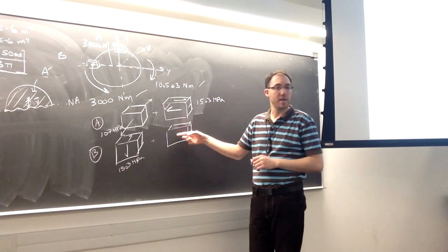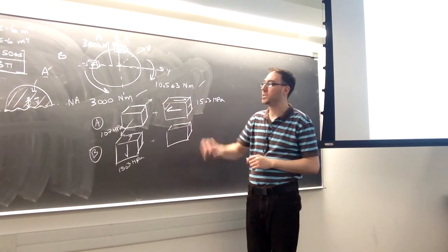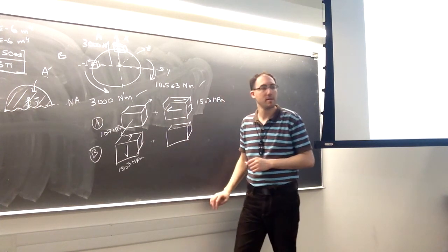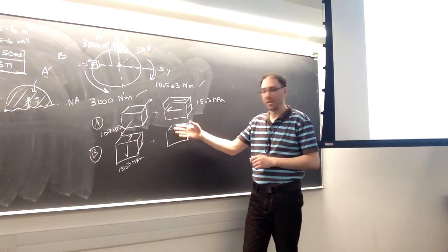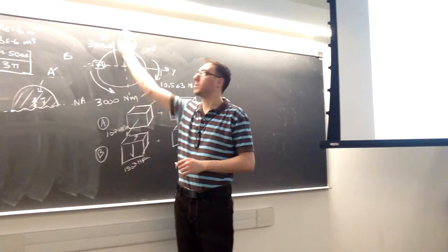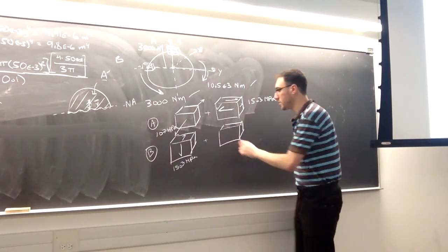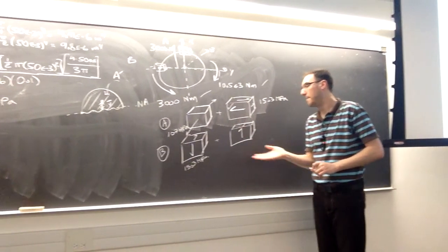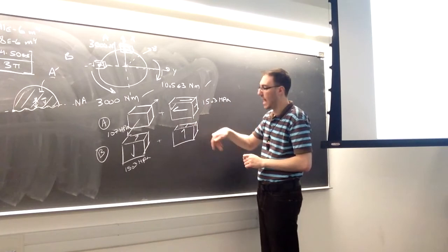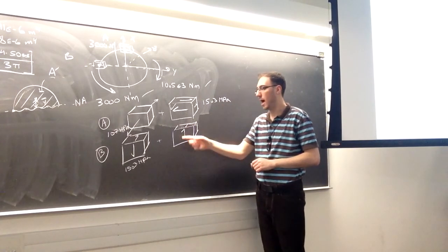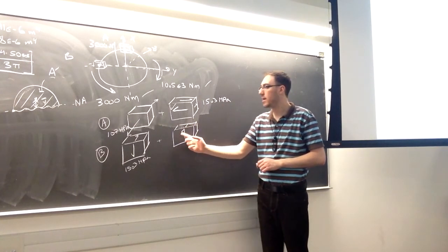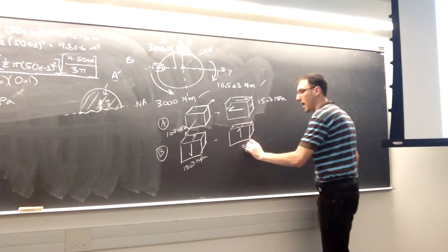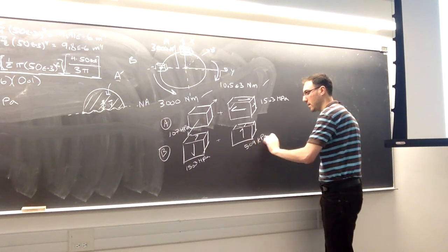Right, so if we look at the stress cube at B from this, what's it going to look like? What kind of stress are we going to see? On the front face, it's going to be in the same direction as that 3,000 newtons. So it's up on the front face, forward on the top, back on the bottom, and down on the back. But really the ones we see are going to be up, and then these are going to be in opposite directions. This is 509 kilopascals.